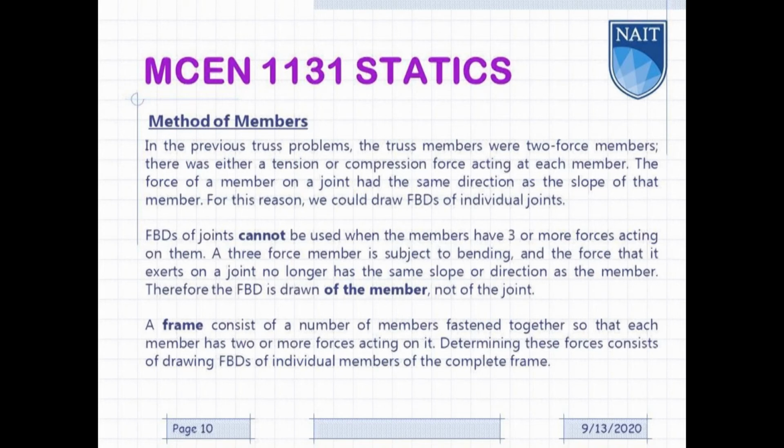A frame consists of a number of members fastened together so that each member has two or more forces acting on it. Determining these forces consists of drawing free body diagrams of individual members of the complete frame.